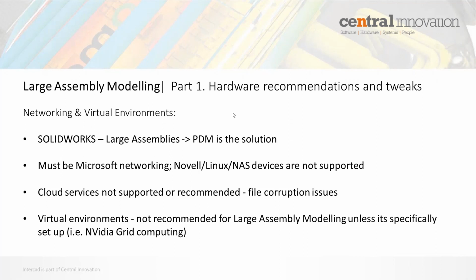Cloud may be fine for storing completed projects, but I certainly wouldn't be working out of those services with live files. And I've seen issues where we've had problems working with files that simply won't save back out of SolidWorks from there, or they become corrupt. So that's cloud services. And just a final point on virtual environments. They're generally not recommended for large assembly modeling unless it's specifically set up, like an NVIDIA Grid computing system. In that, I'd say that NVIDIA Grid or those types of systems are probably a separate topic in their entirety, which, if there was the call for it, we would probably cover in a webinar.